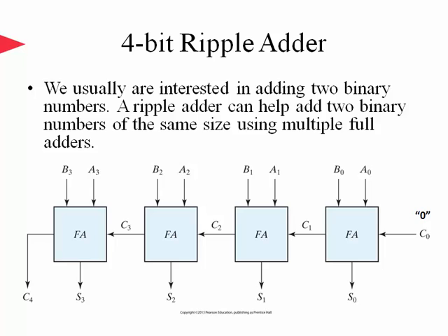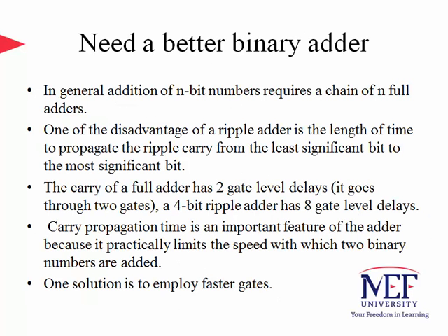The sum bits are generated starting from the rightmost position and are available as soon as the corresponding previous carry bit is available. So all the carries must be generated to be able to see the correct sum bits appear at the outputs S0, S1, S2, and S3. Please also observe that if we were to design the circuit using a conventional way, it would require a truth table with 512 entries, since there are 9 inputs to the circuit. Therefore, an iterative cascade of a set of standard functions leads to a straightforward implementation.